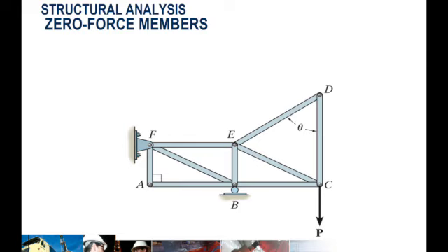Given this truss, by analyzing and doing a free body diagram from certain joints, what we want to look for is a truss joint which is not loaded and is composed of two members. So by inspection, we can say that that is joint A and joint D.